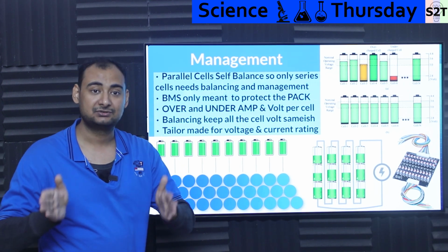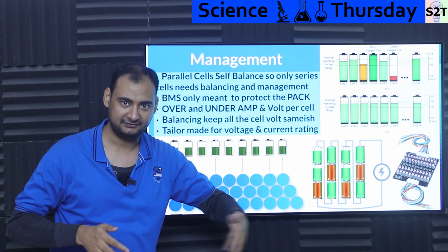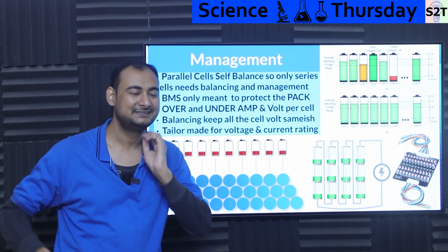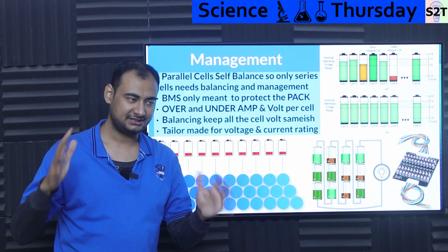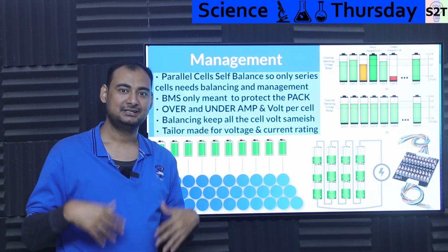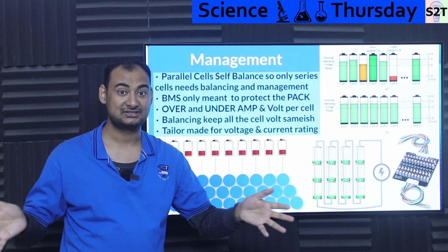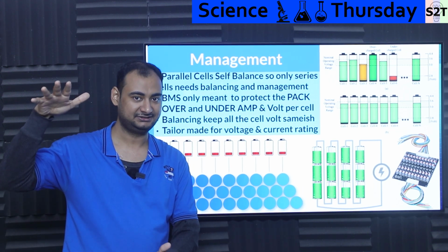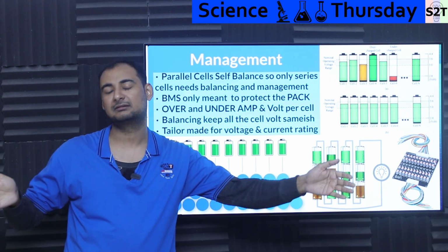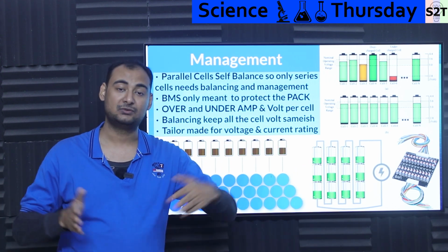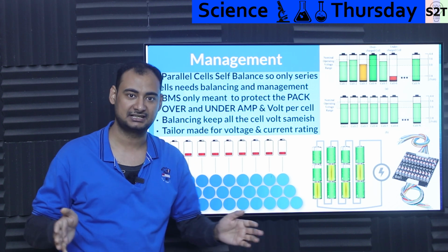And that's how you make sure that after aging, after 5 years, after 10 years, you still have a working circuit. Because again, the cells will age. Let's say you have a chemistry of 500 amps sustained of surge, you do not put a BMS at that limit. You make sure the cell chemistry is always higher. The cell chemistry is the last thing you never want to touch, especially in long run applications. If you want this puppy to work for years, you never push it that hard.